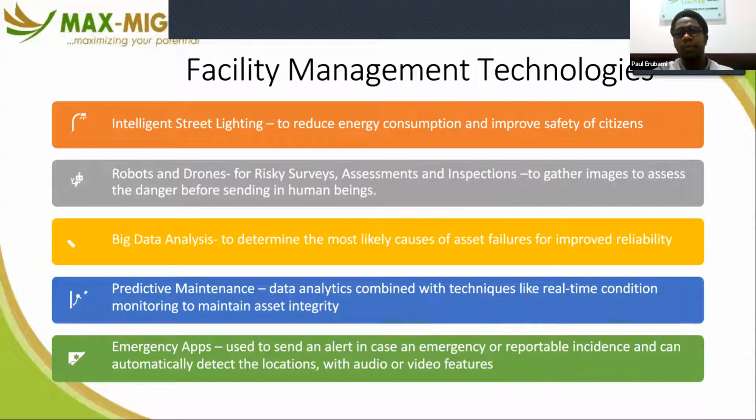It's cheaper now to get a drone to fly over your building and do a condition assessment of your fabric than trying to use rope access and hiring very expensive people to come running around doing those inspections for you and taking records. Besides, with drones, you have a record that you can refer to again and again. It's not somebody going up there and coming back with some notes, right?